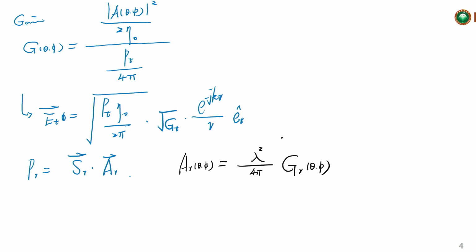So I'm not sure whether you remember this equation here. So this equation is from our previous investigations of the propagation of electromagnetic waves. So this one, and after that, in the case of the polarimetric radar systems, we really used something to represent the beam pattern. All right. So for the single polarized communication, the radar systems, we already use the radiation pattern, right? Use the radiation pattern, and we use the G(θ, φ) to represent that, right? For a typical radar system, we really use a sinc function to represent that, right?